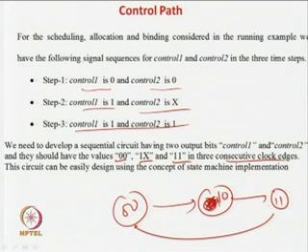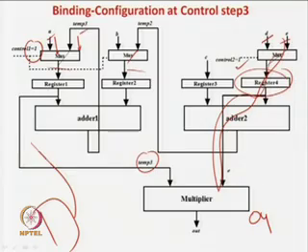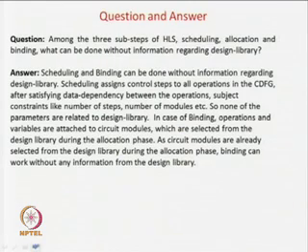And so, this can be very easily synthesized using digital circuit fundamentals, and that will complete your whole RTL design, that is your high level block diagram. So, this is your high level block diagram finally, and there will be another block level diagram which will generate the control sequence. Here we will have this finite state machine which you have already drawn. So, this is the output of the high level synthesis procedure.